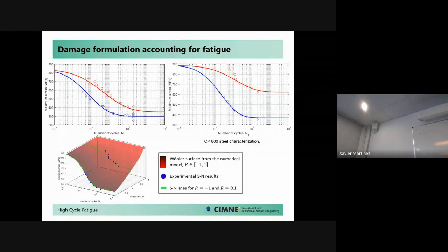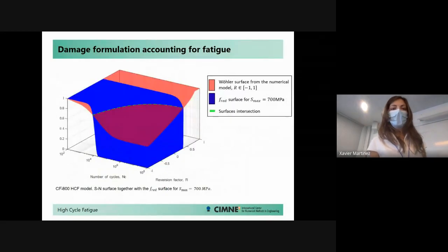So basically, the problem is quantified or defined in such a way in the finite element simulation that each integration point inside specific finite elements that have to move outside of the stress ratios which were calibrated, they will be defined properly with our model. Okay, that was said about the Wöhler stresses, but I also mentioned the reduction function.